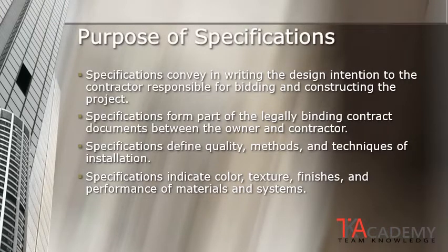So why should a project include specifications? Why can't they just simply use the drawings? The purpose of specifications is to convey in writing what the design intent is to the contractor who is responsible for bidding and constructing the project. The written word is more universally understood, and therefore specifications typically take precedence over drawings on a project.